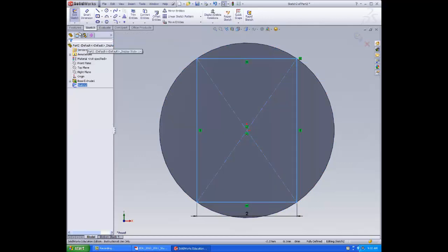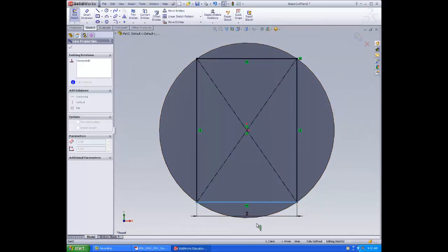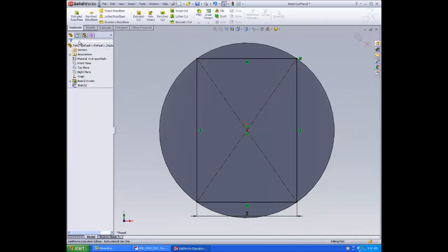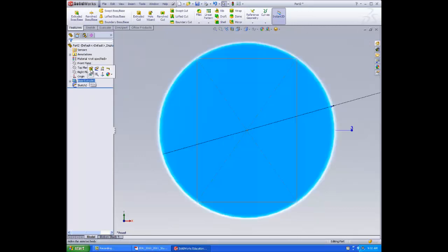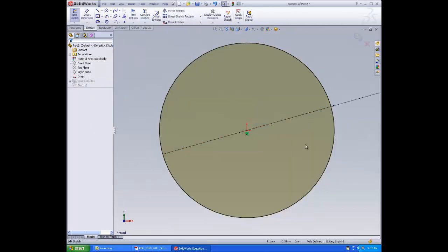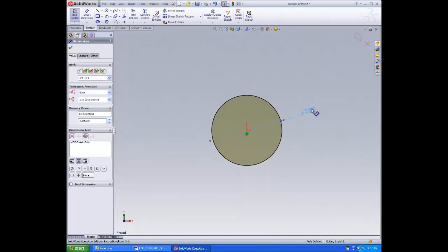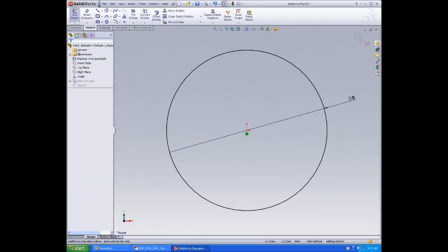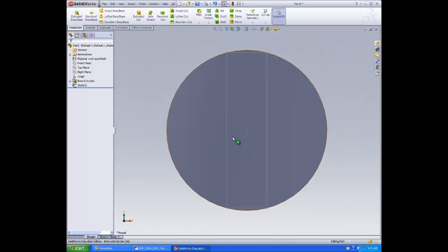You know what, let's cancel, because that has not worked the way we want it. So we gotta actually exit for now. With that canceled, go back into here and edit the sketch. And we gotta set this now to 8. So go into here, delete all other dimensions, and set to 8. Now that's better. So click OK, and exit the sketch.